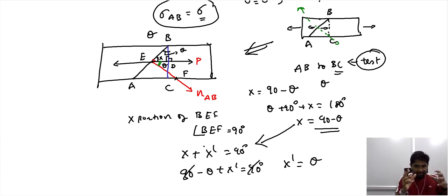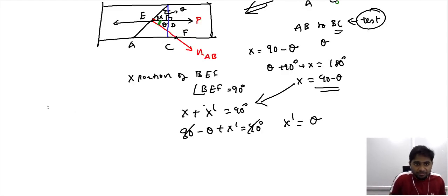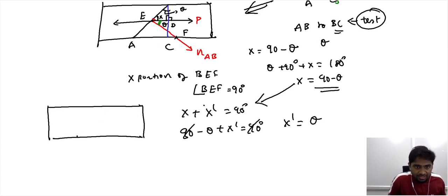So what we have identified is the normal of our region of interest is inclined to the loading direction, and the amount of inclination is equal to how much the overall region of interest is inclined to BC, that is the cross-sectional area. So if you replot the setup that we have been considering so far, we have an inclined region of interest, and when compared to the perpendicular cross-section area, it is inclined by an angle of theta.